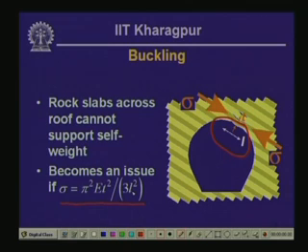All these dimensions are shown on the cross section near the right of this slide. Now, if sigma is less than the value calculated on the right hand side, then there is no problem. If sigma exceeds this value, then the possibility of buckling has to be taken care of in the tunnel design, or supports have to be designed in order to prevent such occurrences.